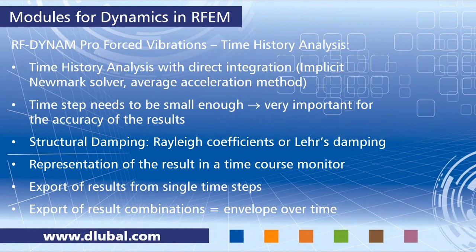As I said, we will have a detailed look into the forced vibrations, into the time history analysis. We have the direct integration implemented, so we use the implicit Newmark solver. Here you also have different Newmark solvers available in the literature. We use the average acceleration method. You could have a look in the literature for further details here. For example, Wilson's Structural Dynamics is just one book I can mention, but there are many good books available